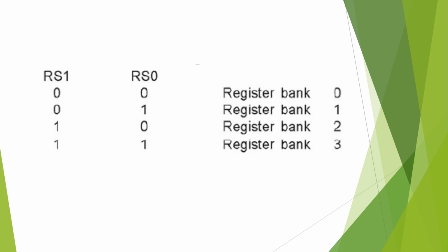Because we are considering 8051, any register contains an 8-bit number. So if D7 is used to indicate the sign of the number, the rest of the bits, from D0 to D6, these 7 bits, indicate the magnitude of the number.